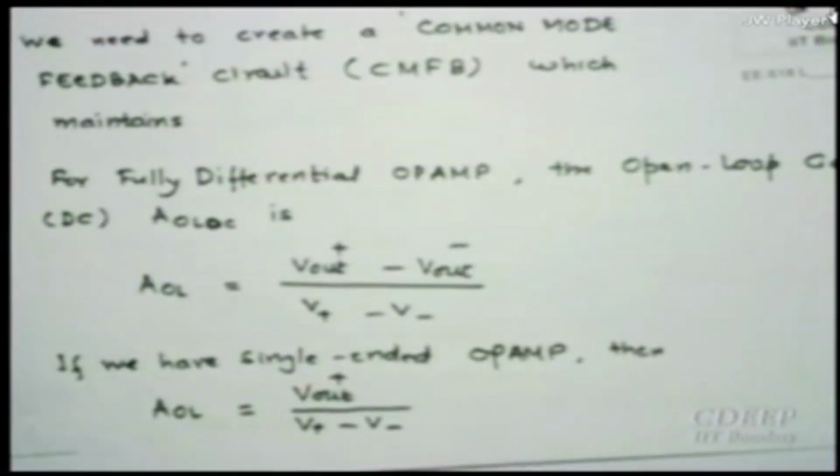There is an issue with what is called the common mode voltage. For CMRR to be high, we want the two devices to be as identical as possible: GM1, GM2, W over L, everything. Then we figured out that the CMRR will be infinite, since delta GM is 0 in the denominator.